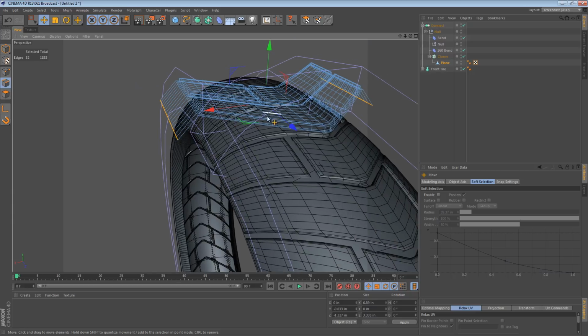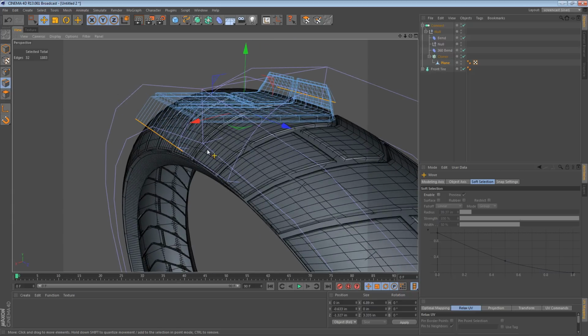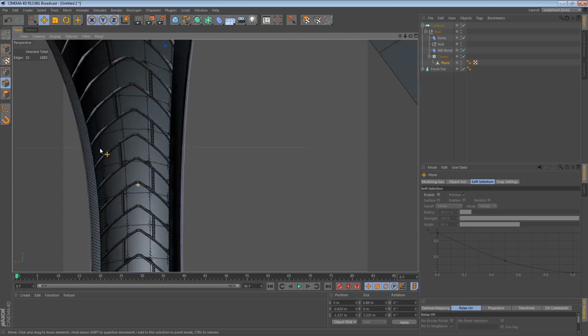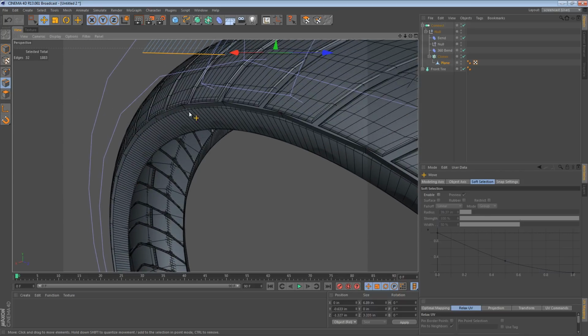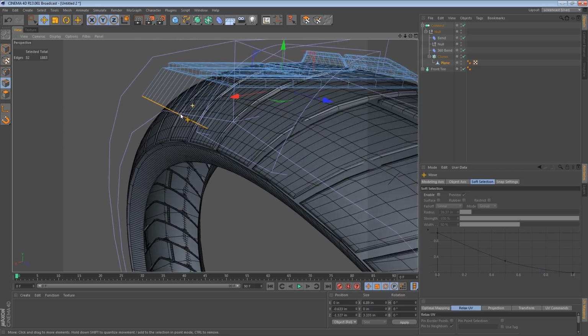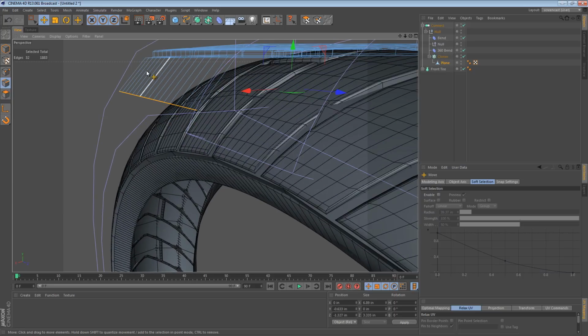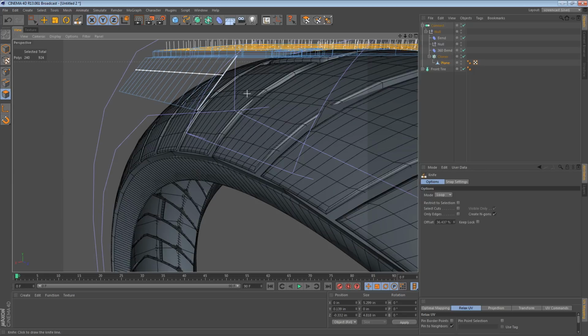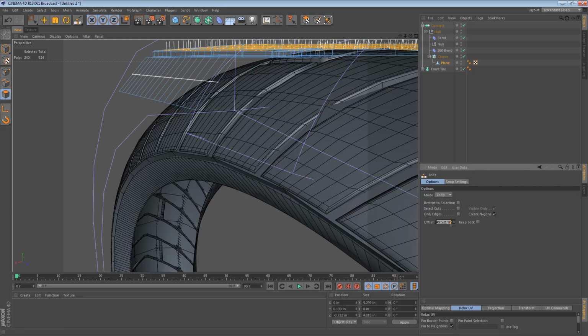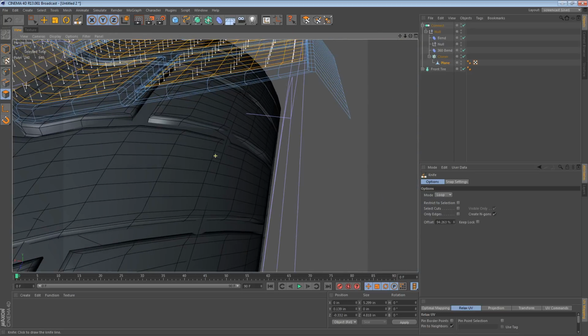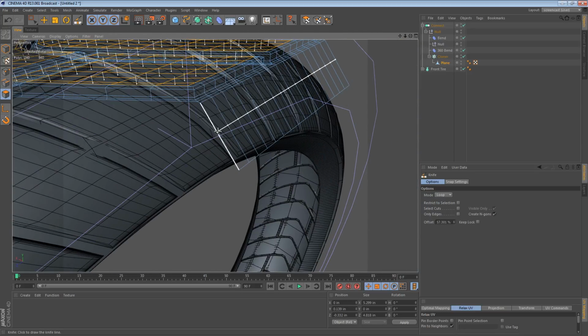The other thing we can do is subdivide these walls once they're sort of the correct size here. As you can see, I have them at sort of the correct size. The reason is because most motorcycle tires have a slight concave or convex shape right here. So we can just use the knife tool. If you tap and release shift, it sticks. And you can actually set that to whatever percent you want, like 50%. Then you click and it cuts it. So we can just do that on both sides. Tap shift and release. Set that to 50% and then click.